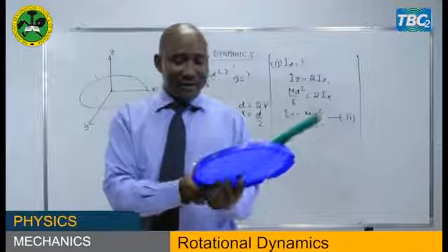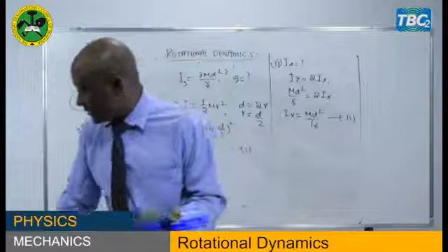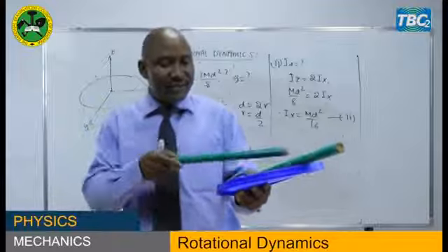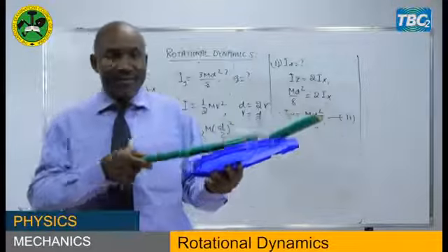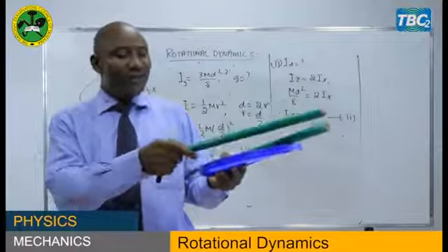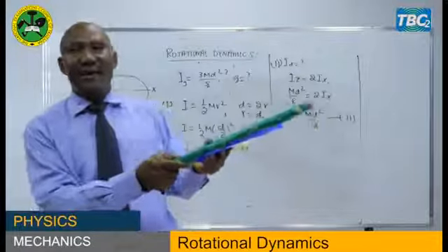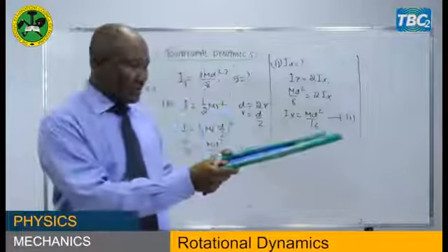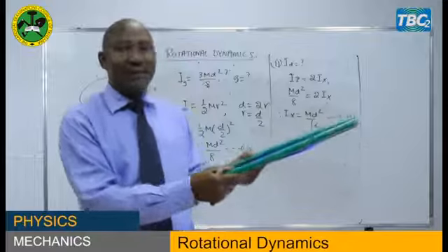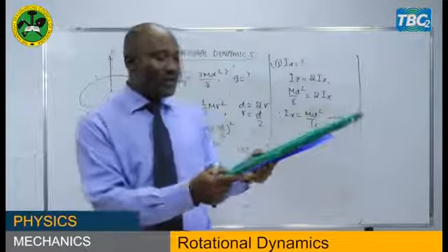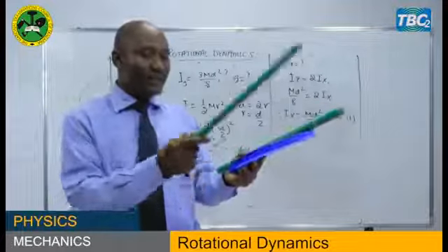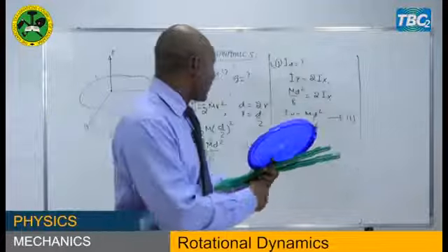We know the formula at the center, and the moment of inertia about the diameter. Since we know this, we can find the moment of inertia about the axis passing through the circumference. The two axes are parallel, so you apply the parallel axis theorem. Let's check whether it's passing through this axis, which is touching the circumference and parallel to the plane. That's case number 3.